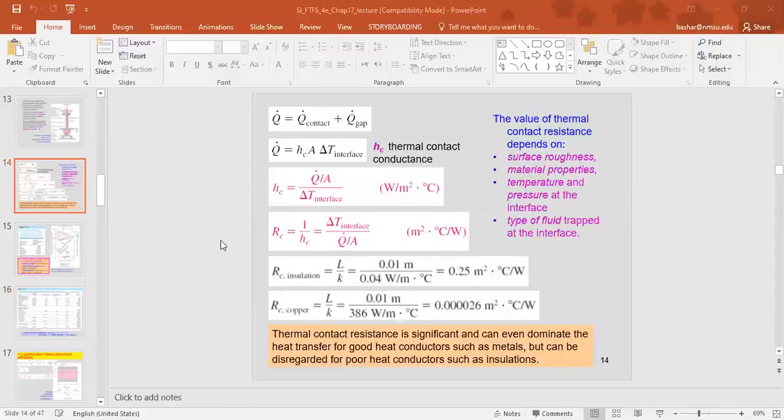And notice here that this thermal contact resistance is actually the thermal contact resistance per unit area. As we can see, it's multiplied by meter squared. Generally, the thermal resistance is simply in Celsius degrees or Kelvin degrees per watt. So here we need to add a double prime, since it's resistance per unit area.